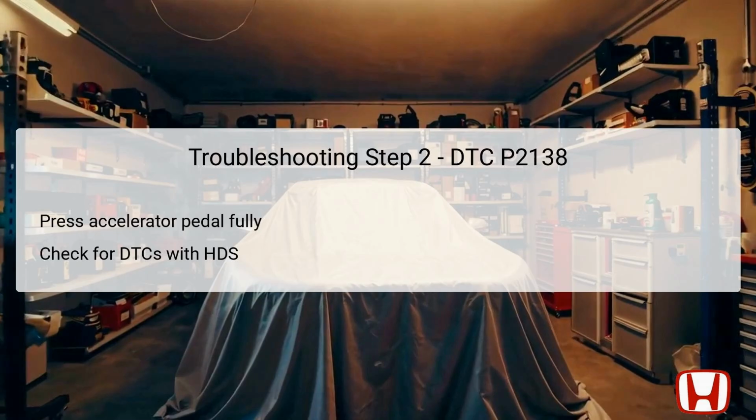On the other hand, if the code does not appear, it might suggest an intermittent fault or a temporary issue, warranting further inspection of connectors and wiring before concluding the troubleshooting process. In this step, you need to check the data list using the HDS to review the voltage readings from APP sensor A and APP sensor B.